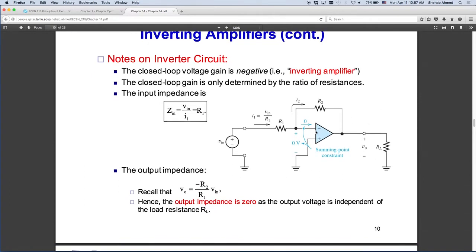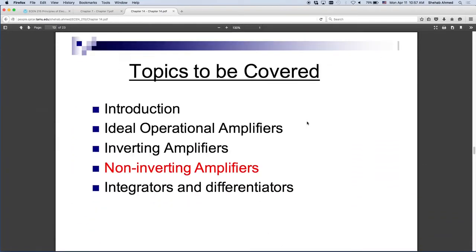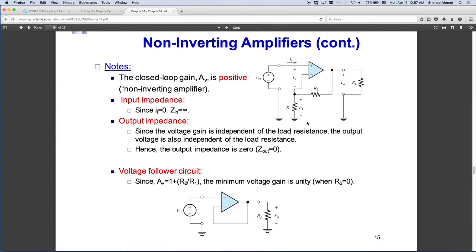Before, it was negative. The voltage was on the negative terminal, right? So then when I brought the output back, before it was negative, so I bring back this negative voltage to the negative terminal. It would be a voltage that will be reducing the input voltage here, versus here, it will drive this to 0. Right here, to drive this to 0, I need to bring back a positive voltage to this terminal. In the other case, I need to bring back a negative voltage to the positive terminal.